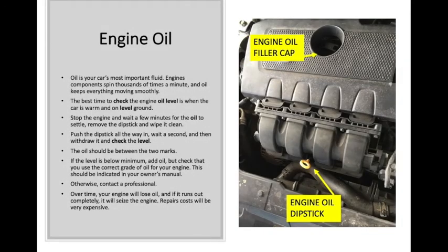Oil is your car's most important fluid. Engine components spin thousands of times a minute, and oil keeps everything moving smoothly. The best time to check the engine oil is when the car is warm and on level ground. Stop the engine and wait for a few minutes for the oil to settle.